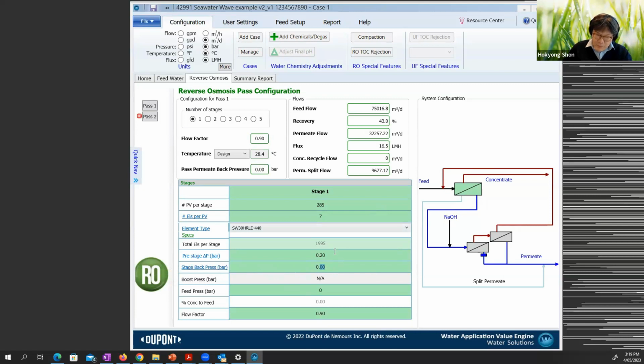So water is flowing, and when you give a 0.1 back pressure, the water is not flowing against the 0.1 bar of your back pressure because you need to balance, because you want to give a more concentrated brine flow rate, because your permeate flow is too much.